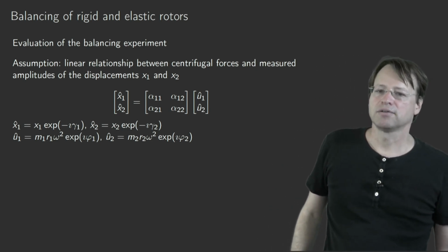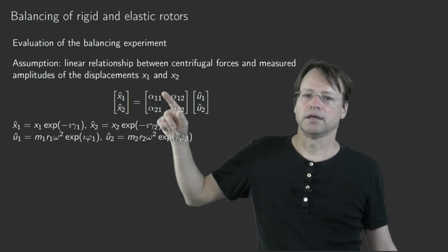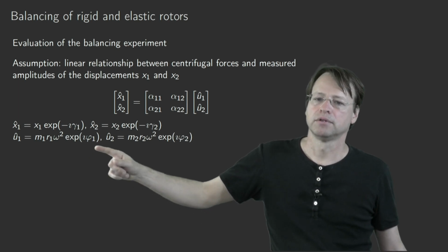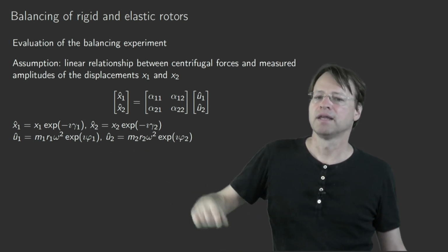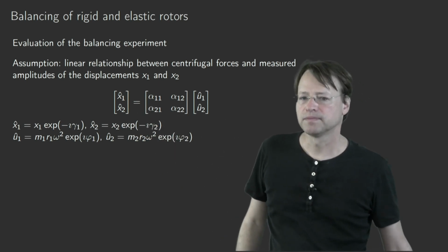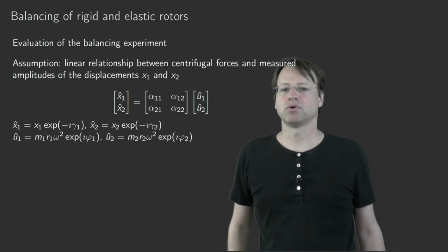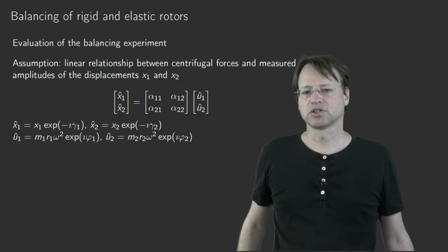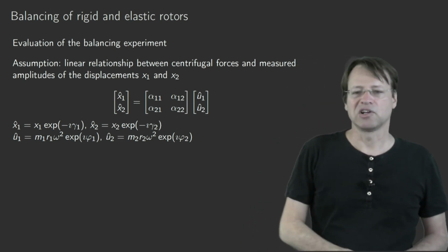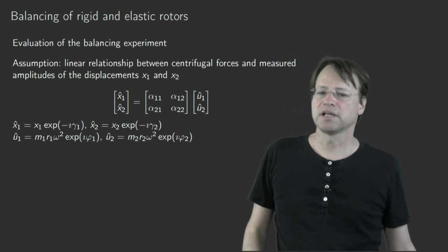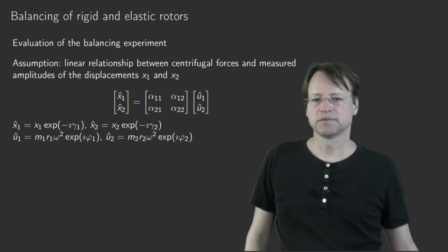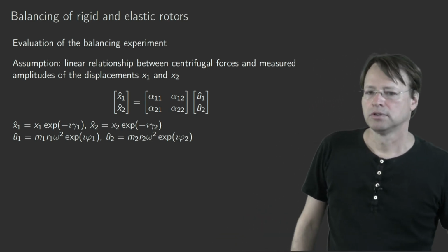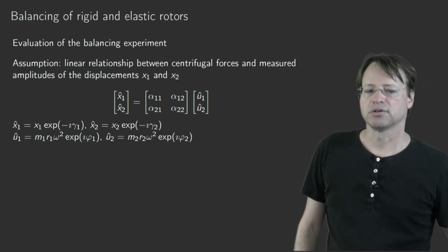And in these planes we can represent the centrifugal forces, U1 and U2, by complex numbers, by a complex pointer, and also x sub 1 and x sub 2 here, so the displacements, by a complex pointer. You can see that this complex pointer is represented by this exponential function, telling you that, well, there's the classical rotation, but that these are really complex numbers because there could be a phase shift. For example, due to some first order terms, to some damping terms included here.